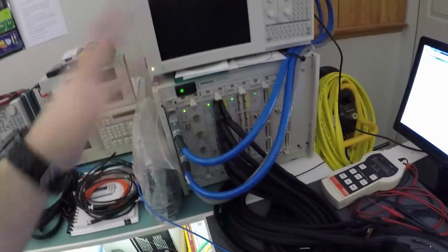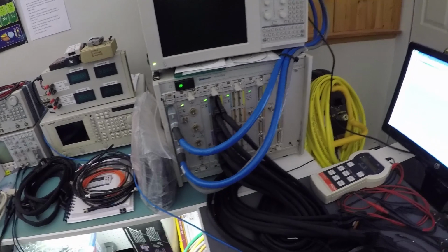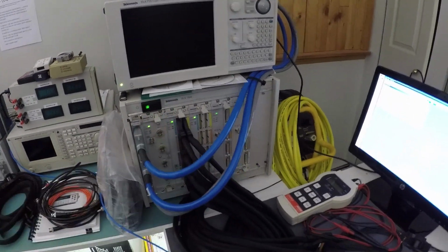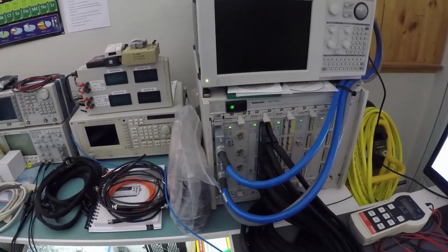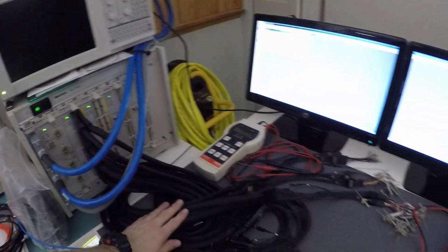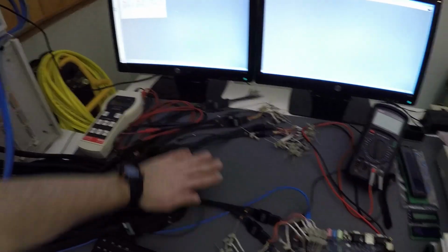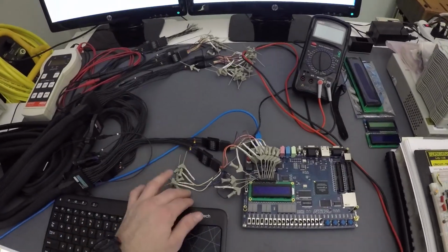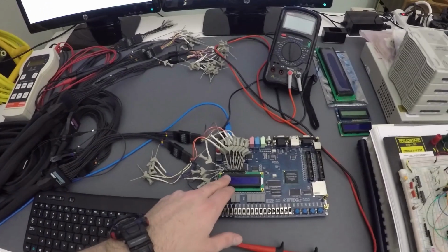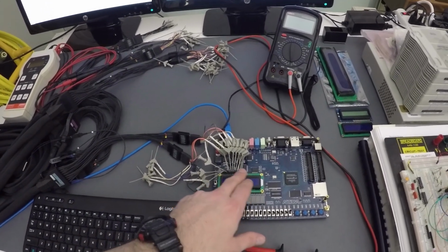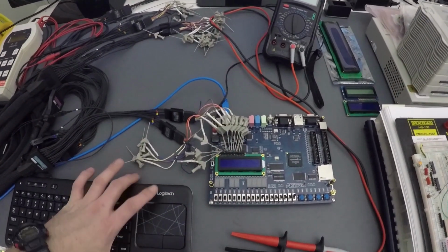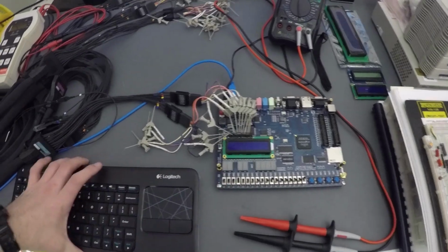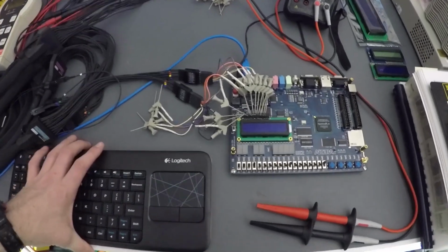But anyway, just to explain my setup, this is just a standard logic analyzer interface from the TLA 715 logic analyzer mainframe, and I've got all my cable lines here, and we're only going to be using various signals to monitor the databus, the 8-bit databus coming off of the HD44780.